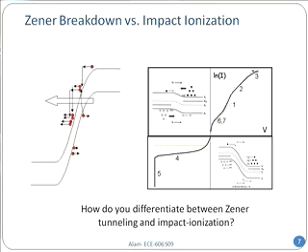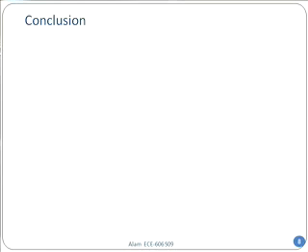There are lots of traps sitting there, you'll have to fix it, right? And region 7 was again a tunneling process, the ECE606 tunneling. You remember how under heavy doping condition, electrons can flow from the conduction band to the valence band of the other side, an extra current component. It wouldn't happen in lightly doped samples.